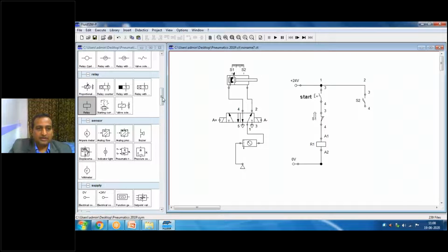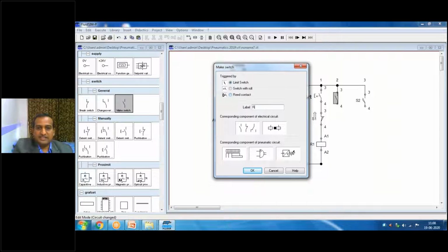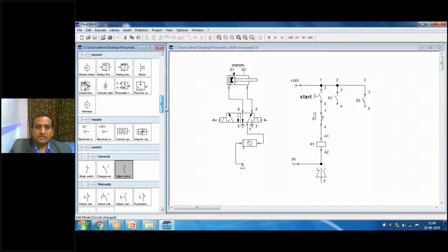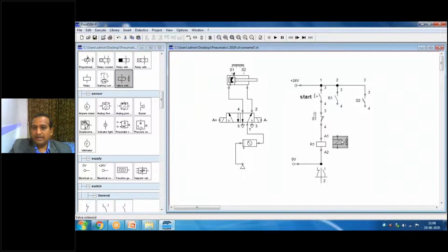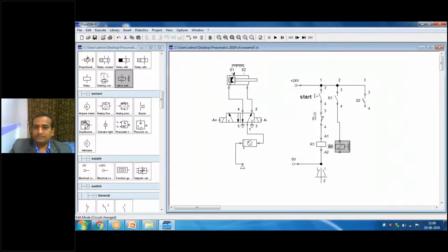R1, when R1 is on, make a switch, a logic switch. This is called a logic switch, not a physical switch. Now, whatever I am showing now, R1 is what? A logic switch. So here, I am taking output from the relay R1, R1 to what? Solenoid valve. Now I am not using the solenoid valve directly. Through the relay, I am using the solenoid valve. The load that comes on the solenoid valve is handled gradually and safely, so that is the better way, we have to use a relay. Okay, A plus. And suppose second, without relay.